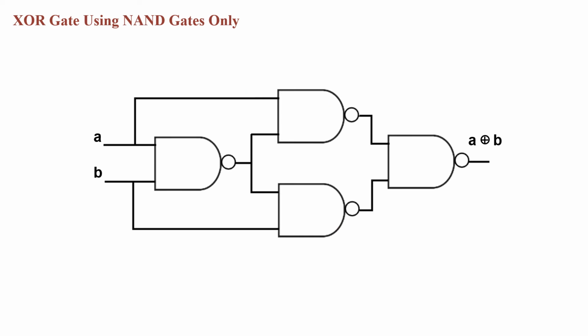So this is the final answer that you will see. It's a sketch of the expression we saw earlier. All these four NAND gates are connected in a way that they're all acting together as A XOR B, or as an XOR gate actually. We can put any inputs here in the beginning, and the output will be the result of XORing them together.